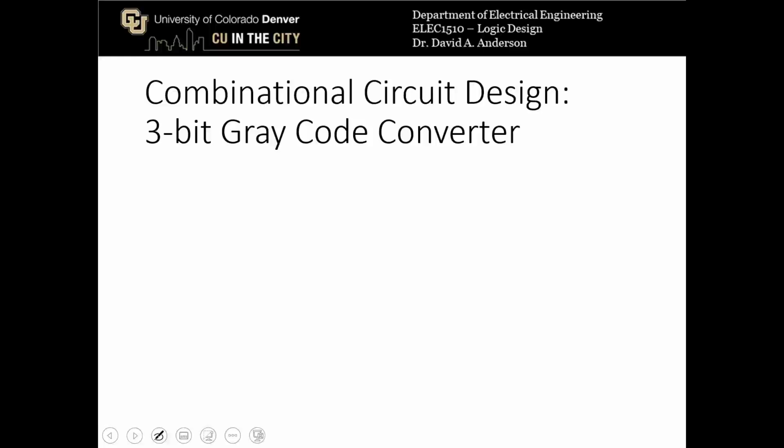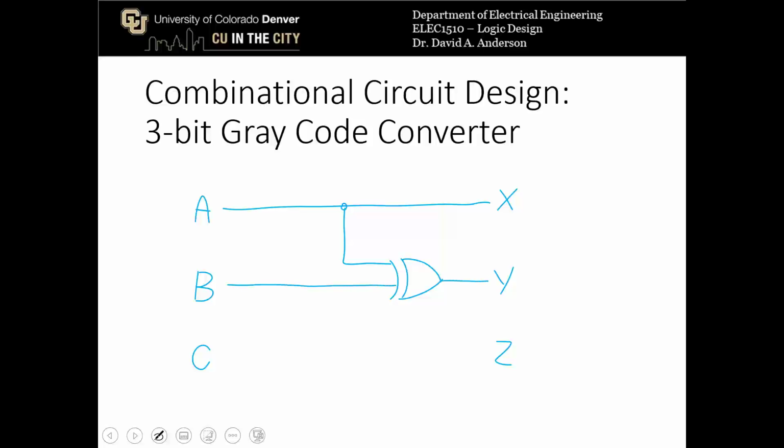So now we want to draw the combinational circuit for the 3-bit gray code converter. We have input variables A, B, and C, and outputs X, Y, and Z. The output X is simply equal to A, so we can just draw a wire connecting those two variables. Y is going to be equal to A exclusive OR B. So the XOR gate looks like this, and we will connect A and B. And Z is equal to exclusive OR of B and C. So we connect it like this. And our combinational circuit for the 3-bit gray code converter is complete.